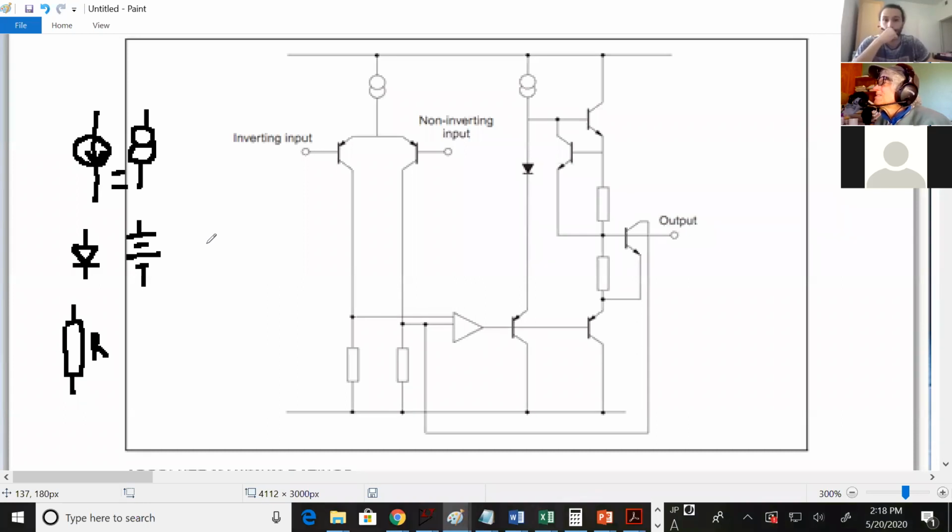Anybody remember what that's called? Or what the circuit was? Push pull? Push pull. Okay. And then you had to shift up and down by VBE on. You needed to get 2 VBE on between the two transistors in the push pull. And you level shifted. What did you use for a level shifter? Common collector? Exactly. Okay, so you used a common collector.